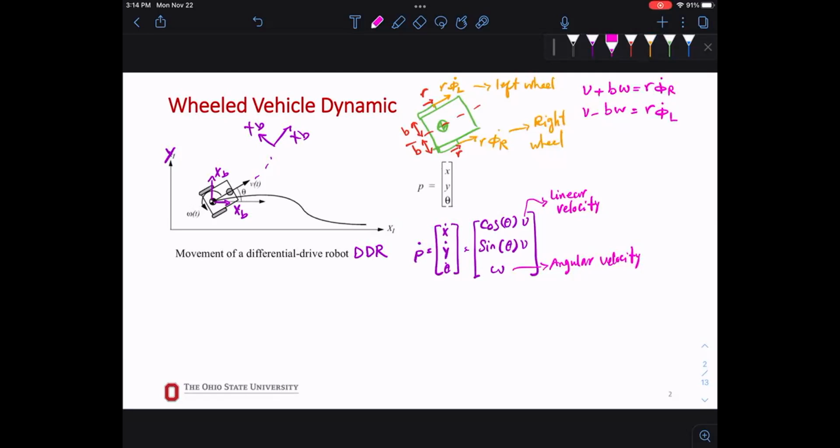So basically controlling the motion of a wheeled robot comes down to the value and the direction of the wheel velocity, right? Agreed? Okay, now let's write the dynamics for this. When we have a DC motor for our car, for the wheels, we definitely have torques for each motor. So torque is not going to be zero here. We're going to have torque. So I'm going to call this tau left and tau right, TL and TR.